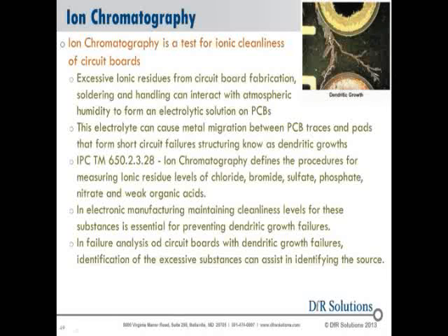They grow from the anode to the cathode until they reach out and touch something and become first a weak and then eventually a strong short circuit between some pads or circuit traces. So this will take out your circuit board and just ruin your day with some kind of malfunction.